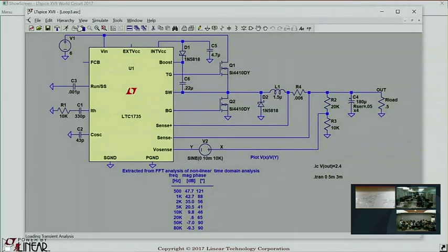It can't oscillate, but you are infinitesimally close to oscillating. So if there's any other phase shift in the system, like a delay, like this part here, okay? This part converts that voltage to a current coming out of the switches. That's actually why you buy that part, because it does that. And when it does that, it's got to have some delay.